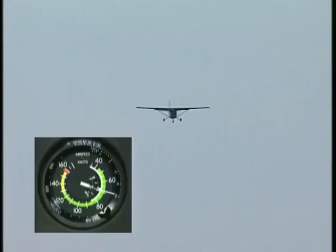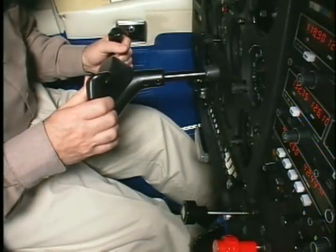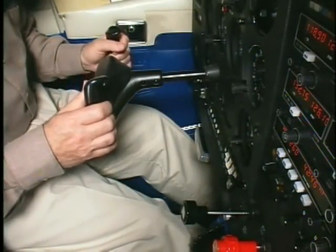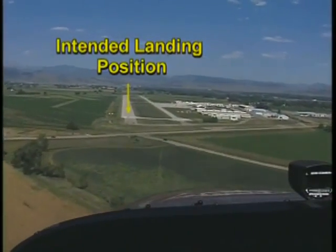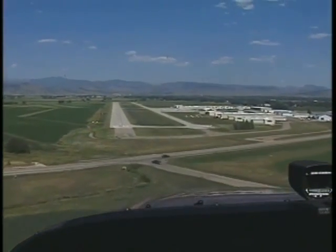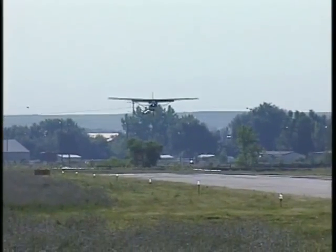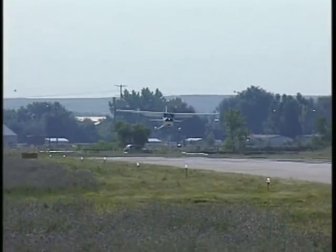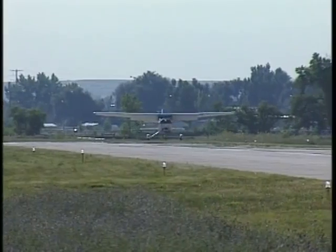Remember, in a power-off situation, the pitch attitude controls the airspeed, which in turn controls the glide of the aircraft. Lower the flaps as necessary and make small adjustments to the pitch attitude to control your glide angle and airspeed. While your goal is to touch down within 200 feet of the point on the runway, but not before it, with little float, do not attempt to stretch the glide or retract the flaps in order to make the landing point. Concentrate on making a safe landing, then re-evaluate your downwind and base locations and flap positions for the next power-off approach attempt.